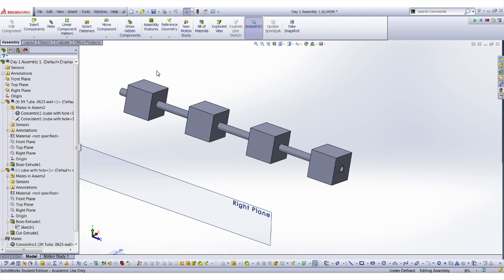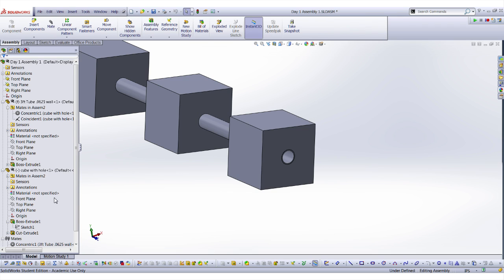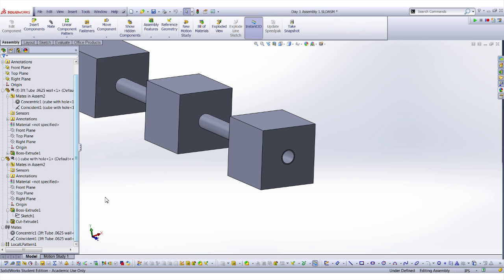Yeah, how do you keep the circle concentric? So, okay, keeping the circle concentric. That's just basically determined by how you've drawn things before. As you start getting better and better at it, you'll learn what SolidWorks will be able to update and what features you want to stay the same. So if you knew you wanted to always keep it centered, but the dimensions might change, you would draw it to where you didn't dimension it. When you drew it, you dimensioned it 2.5 inches off of 2 walls, it's going to always put it 2.5 inches off of 2 walls.